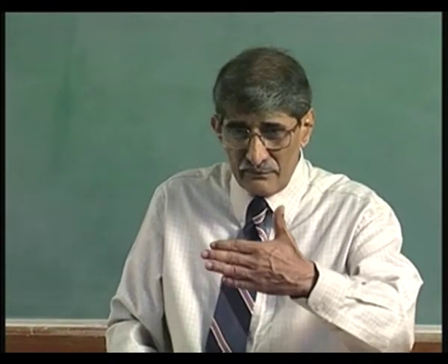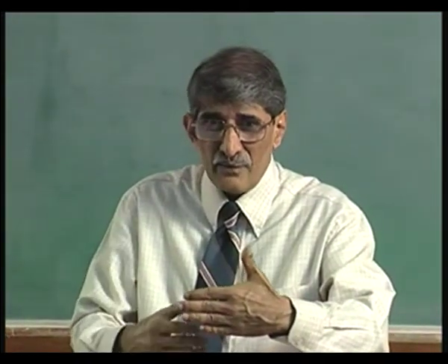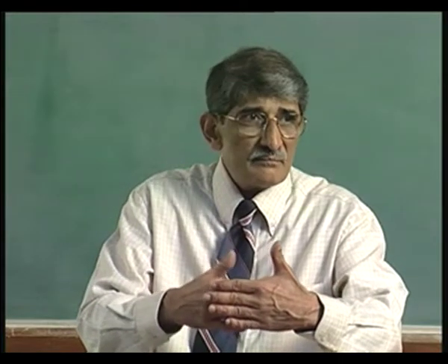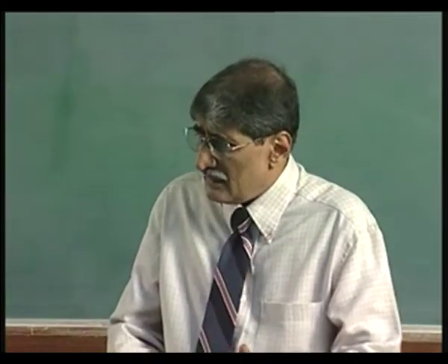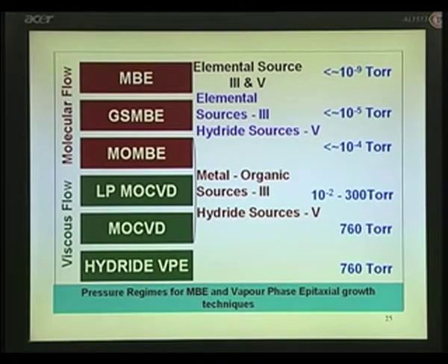And when you mount the wafer vertically, you have the benefit that any particle that is present will not stay on the wafer, it will fall down. That is the benefit of that. That is why people advocate for low pressure CVD systems, where the pressure is not very high, not very low either, 10 to the power -3, -2 torr. Then you have MOMBE etc., where the gases are coming in, there the pressures are not that low during the deposition. Please remember, these are the pressures during the deposition. Before you start, you better pump down to 10 to the power -10, -11 to avoid any contaminants.